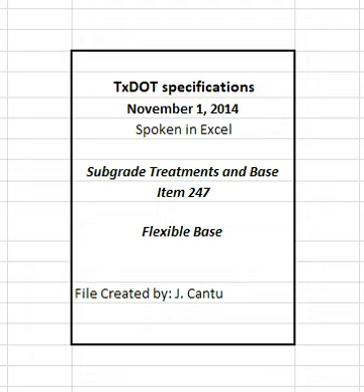The volume of base course is computed in place by the method of average end areas between the original subgrade or existing base surfaces and the lines, grades, and slopes of the accepted base course as shown on the plans. 5.4 Square yard. By the square yard of surface area in the completed and accepted final position. The surface area of the base course is based on the width of flexible base as shown on the plans.